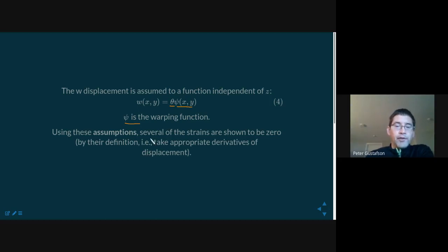Now, so in summary, what we've done is we've observed something about the deformation that occurs in the cross section. We can relate it to the overall amount of twist that occurs. Really, it's a rate of twist thing, and then you integrate over the length of the domain. So it's proportional to the rate of twist and has to do with your position within the cross section.